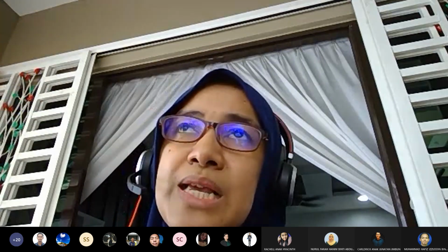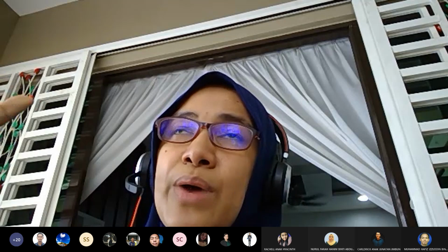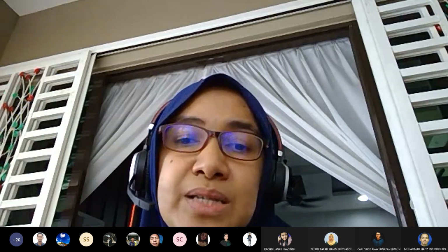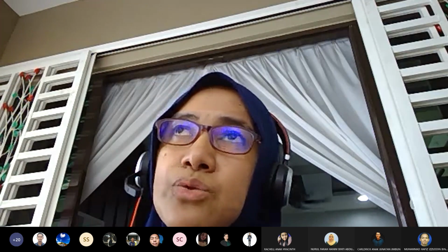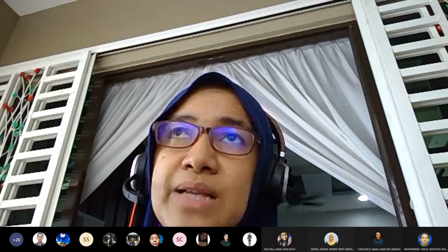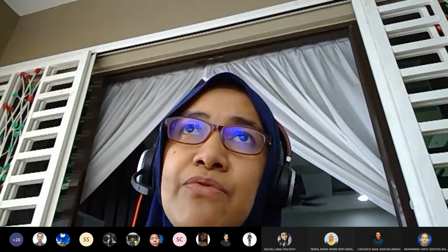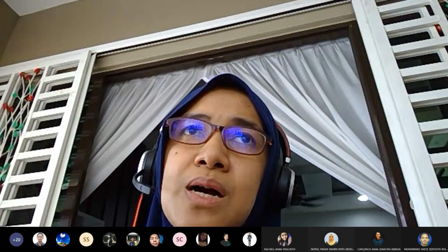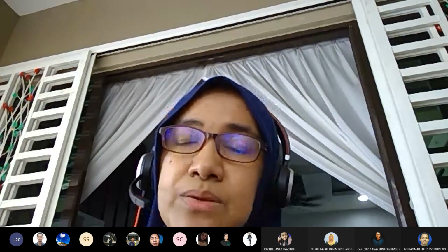I plan to explain about the settlement, the concept of settlement, because the process will be the same in the table, except now we need to consider the settlement whenever we want to calculate the fixed end moment. So fixed end moment actually comes from two conditions. One comes from load, and another one comes from delta. Two conditions.